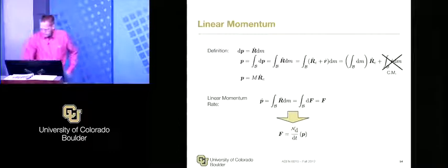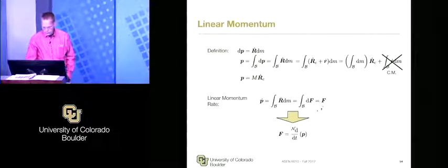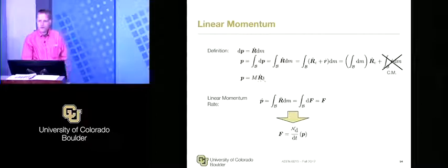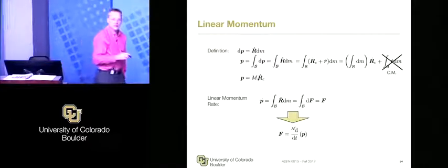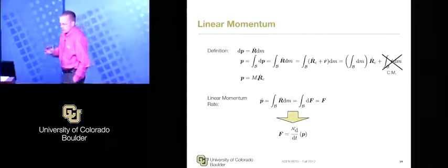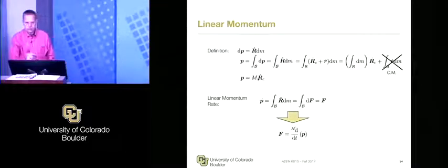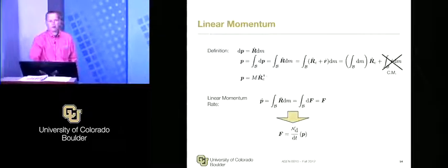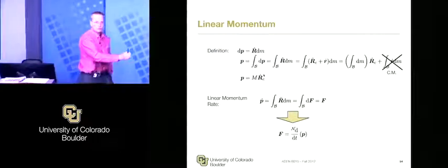How do we get F equals ma out of this stuff? The linear momentum of the system is here, right? P is equal to this. And if you differentiate this, you get P dot is equal to m times RC double dot, assuming m is constant. If m is not constant, you'd have an m dot in there. So F equals ma is true if mass is preserved. If mass is not preserved, this is a more rigorous fundamental property of one of Newton's equations, that the inertial derivative of linear momentum gives you force.